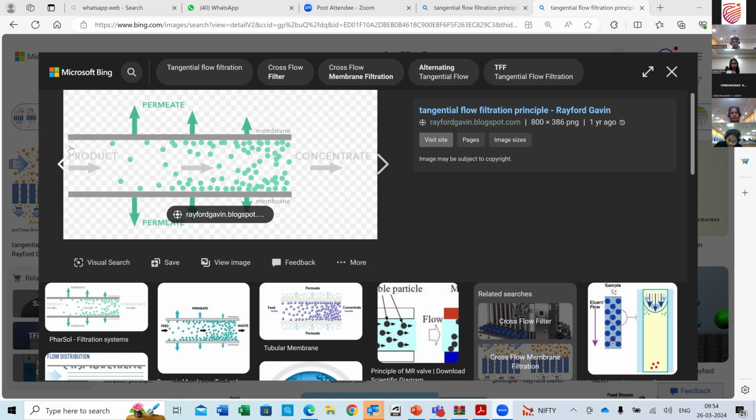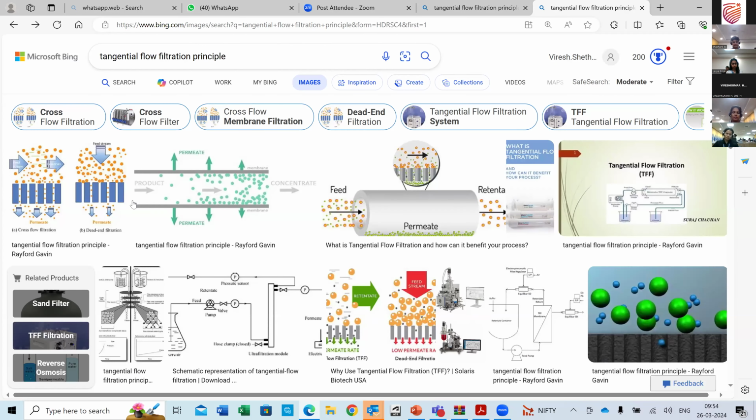and this tangential flow is also causing the filtration to occur. So this is a forced flow, which is you are pumping this flow here, and it is moving, and then it is going back in this loop here. And while doing so, either the product of interest or the waste is getting filtered out. So tangential flow filtration is a technique used for filtration. It is a methodology, just like you see a dead end filtration.